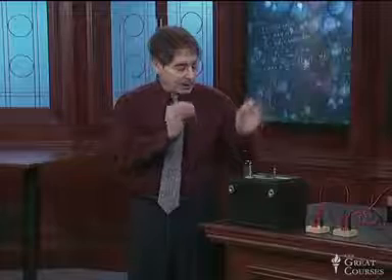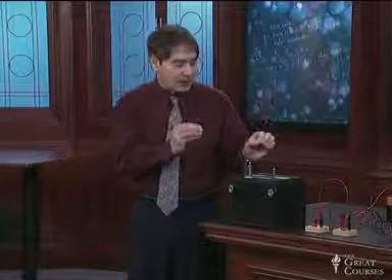And if you want to use a battery and make it work well, you use it in such a way that the internal resistance is low compared to the load you're connecting across it. Okay, that all came from series circuits. Let's now go back and look at parallel circuits.